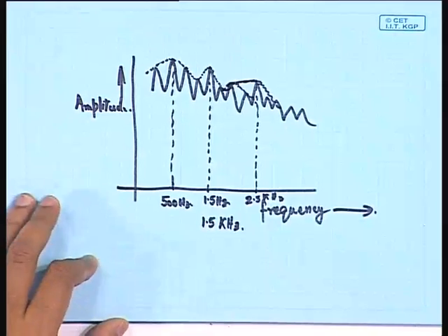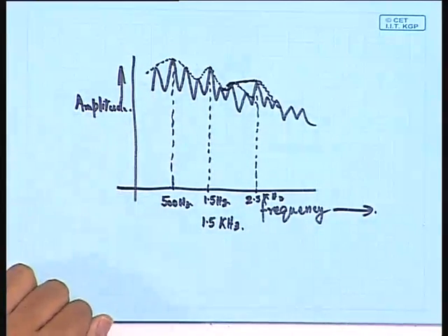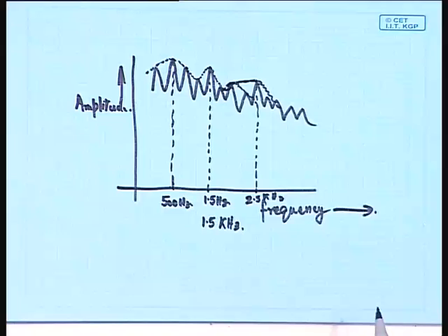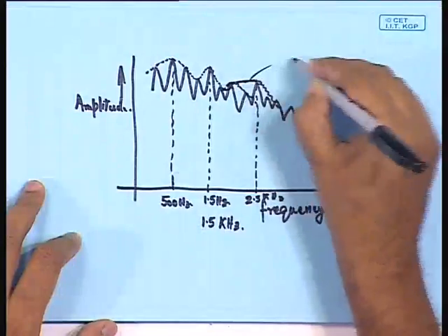So, the amplitude spectrum would be something like this, whereas if you are considering the excitation model directly, your excitation signal has a very flat spectrum, but after the pulse shaping through the vocal tract, because as I have been telling you again and again, the vocal tract acts as a filter, and very precisely it is a time varying filter, this would give rise to a spectrum like this.